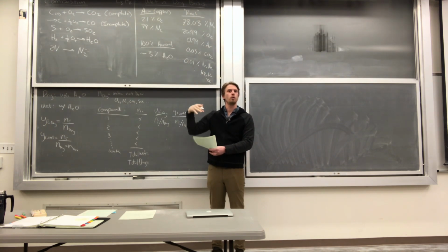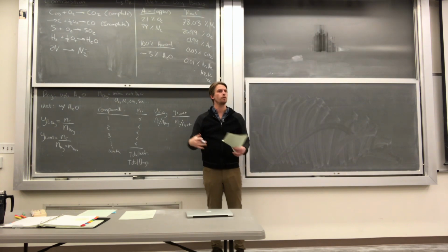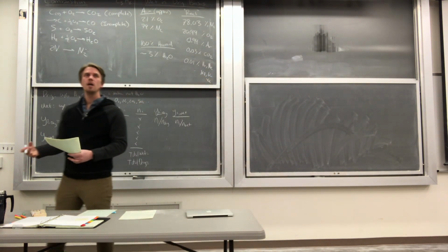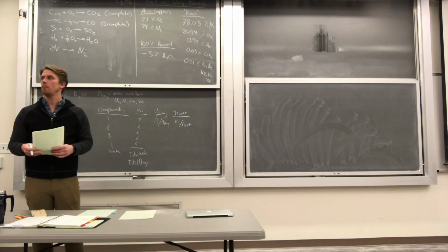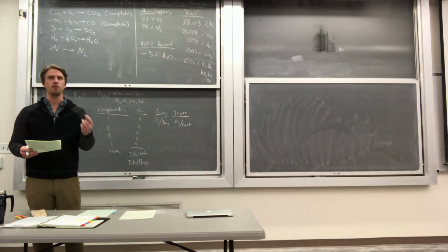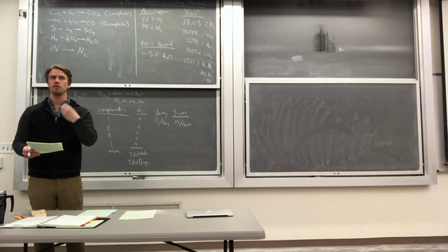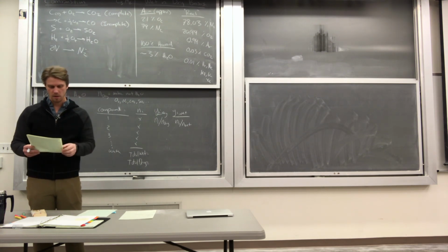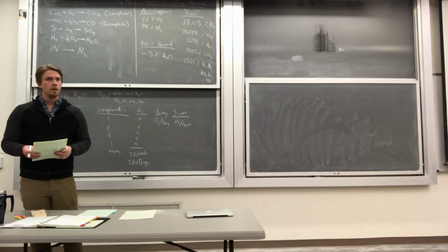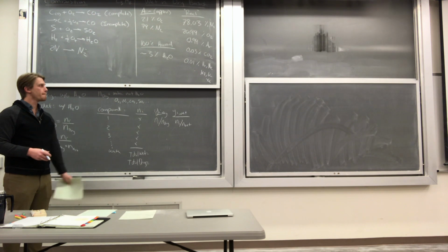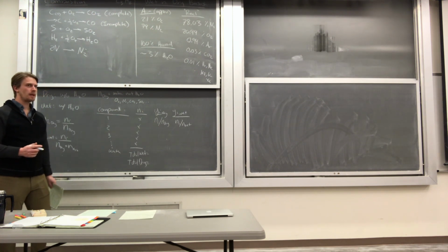So if we were to translate this information across regions, that would hold true. But within our specific region, we would want to consider what's the actual composition of oxygen based on the relative humidity, because you may need to adjust your air to fuel ratio if it's a humid day versus a not humid day. Yes? So what does relative humidity mean? How do you convert between percent humidity to percent composition?